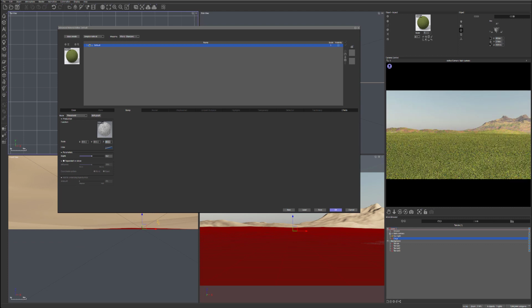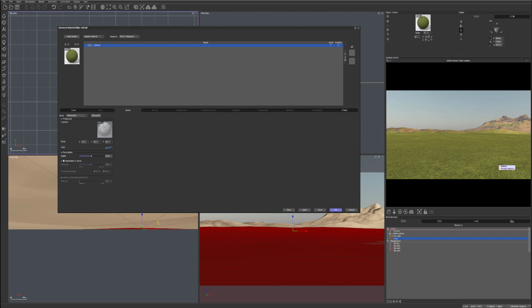So make it even smaller grain. Also, depth is a little bit too high, so I think 0.05 depth will do. We don't want too much of this bump map, we just want it slightly touching. Again, bump map does not change shape or add polygons or anything, so it's in render. It will be a little bit lighter for our produce.